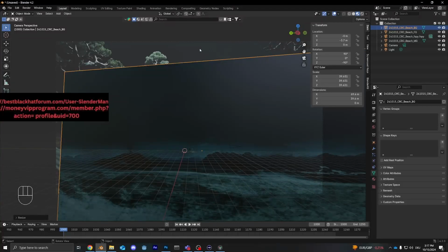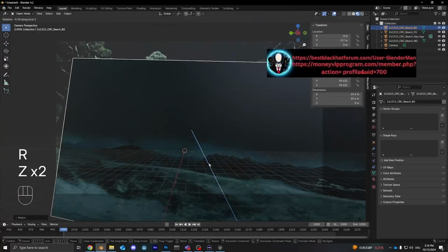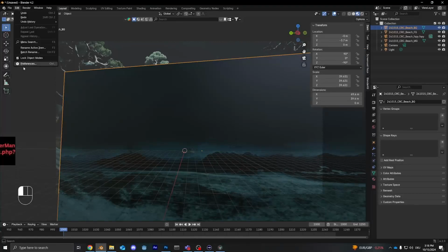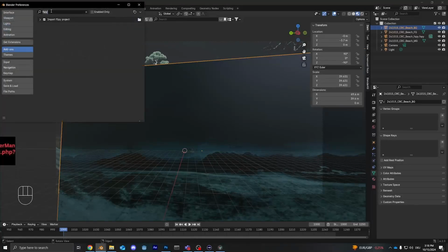Now you'll see, because the camera is crooked, because that's what FSpy did, this is not aligning perfectly to our camera angle. But we want it to, right? Because the background picture is angled that way. So instead of trying to manipulate this manually, we're going to activate another add-on that's already pre-installed. For that, we go to Edit, Preferences, and Copy Attributes menu. So we turn that on. Down here, make sure to save preferences.